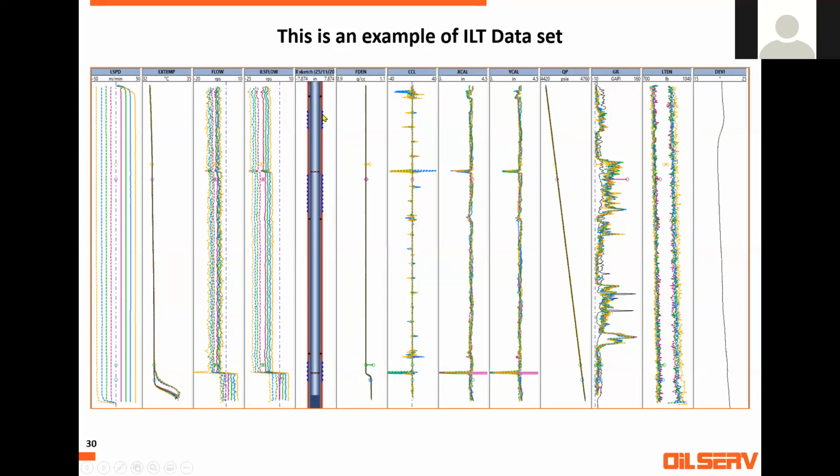Yes, exactly. So what's happening here? This one is isolated, there's nothing going there. This SSD number 1 has only a tiny injection going to it, distributed over these 2 perfs. Tiny is nothing, so these 2 perfs are actually taking maybe 10% or 5% of the injection. All the injection is going to the lower zone.